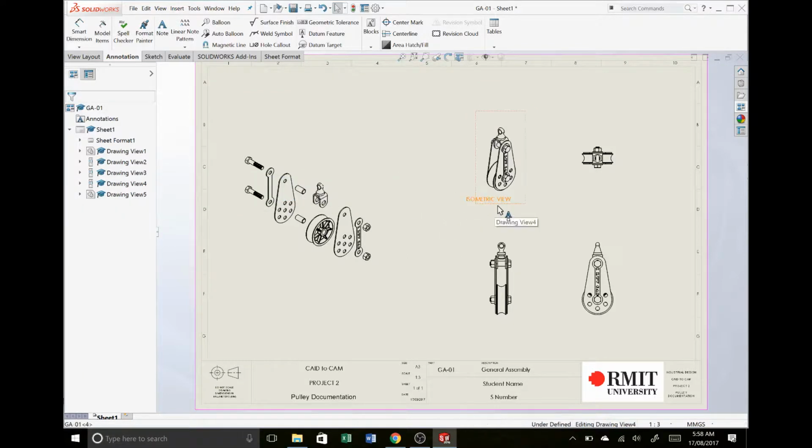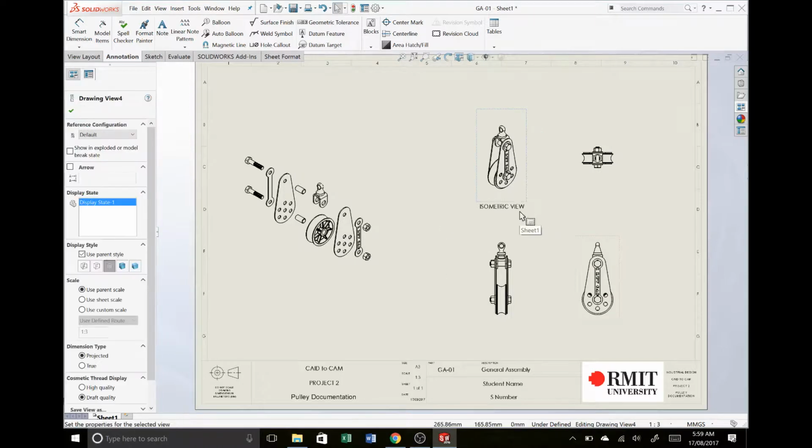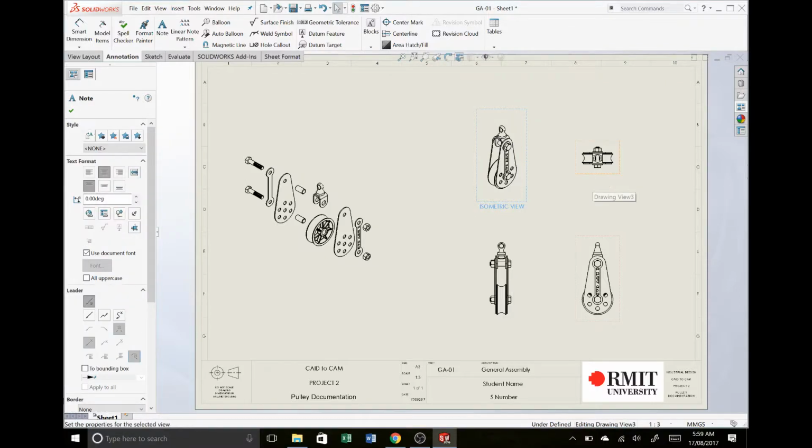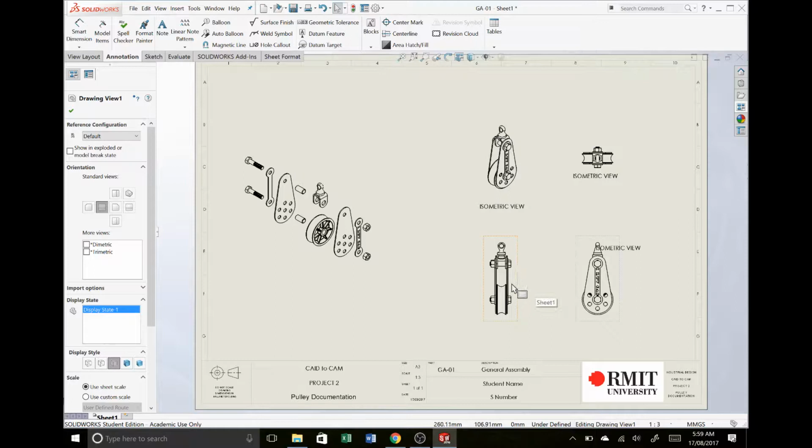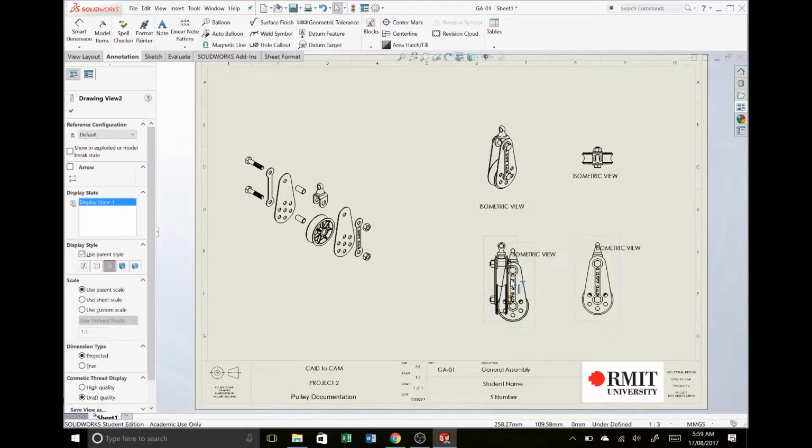and now if I just reposition that text, I know it's already linked to the drawing because it linked when I first created it. I can place that text effectively anywhere around that part, and if I start moving that drawing, the text moves with it. That is the advantage of linking your text to the view itself. And so to keep going, I can just copy and paste that text I've already made since it's got all the settings I like, and I'll just click on a new view that I want to link my new pasted text to, and you can see as I click and drop using Control V there to paste.